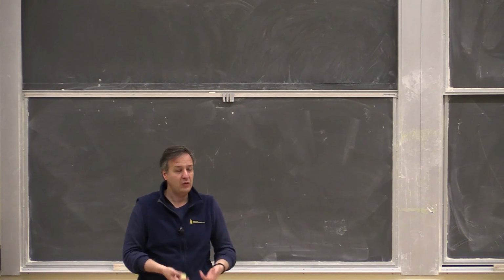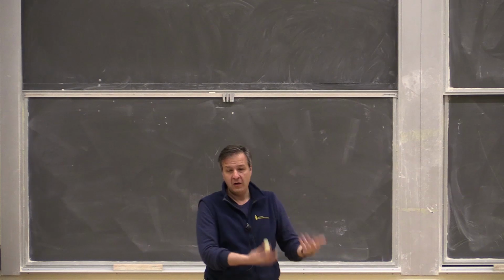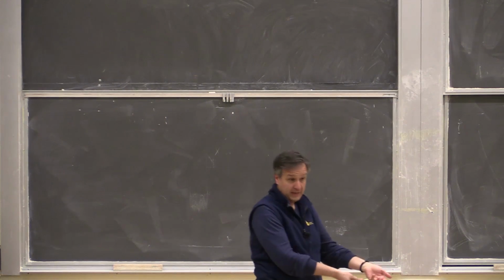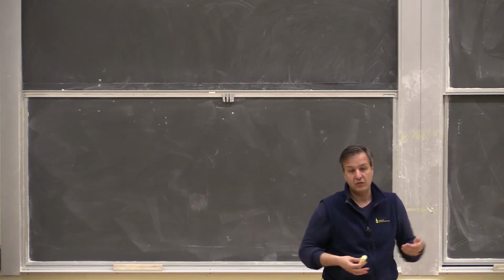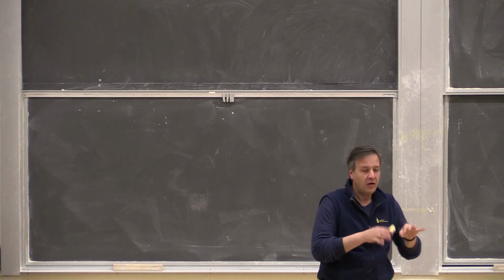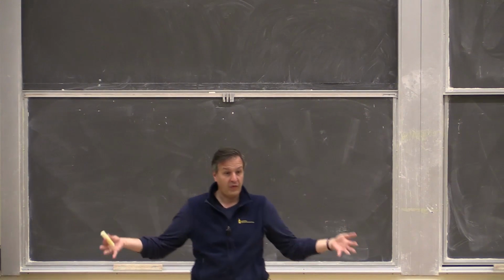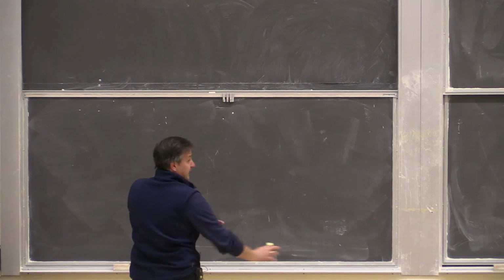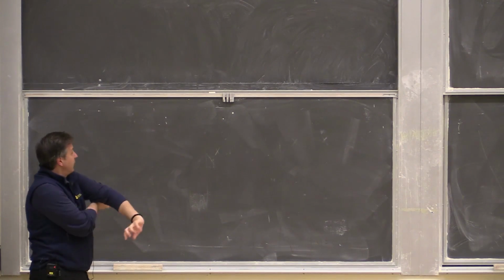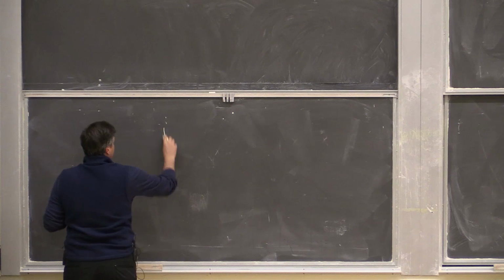Say, I want to add two numbers. Oh, there's this topology for a summing amplifier, right? So I'm going to use that and then think what it does to the rest of the circuit, rather than go and write out a detailed 10-node nodal analysis for the whole thing. Okay? But one step at a time. So we're going to start just revisiting a little bit the inverting structure.